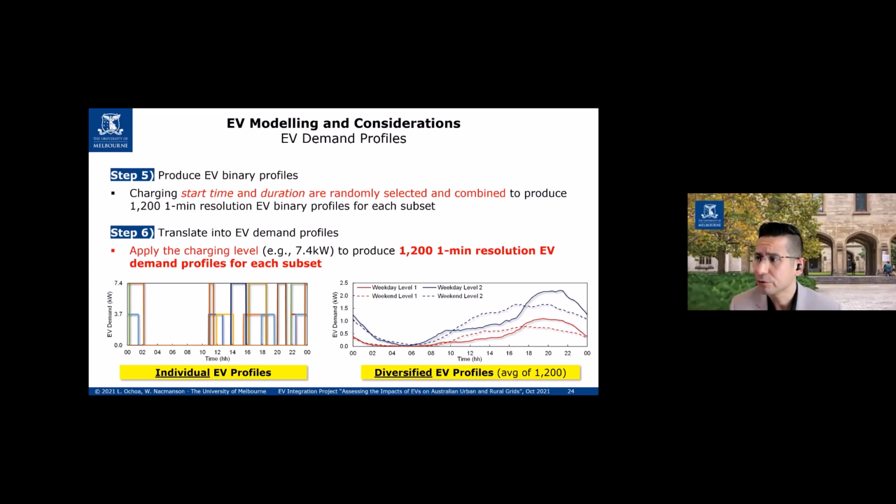Are voltage issues reduced with three-phase charging? That's a great point, Peter. I believe so. Voltage issues will be reduced with three-phase charging, and the reason for that is that unbalance plays a role here. Everything that we have done here are with single-phase connections, and that has the chances of increasing unbalance. If you have three-phase charging, it means that it will be balanced among the three phases, and that will have lower impacts. We know that for sure. We know that already with solar photovoltaics, so the same thing will happen with electric vehicles. Now, you cannot suddenly change the single-phase connection of houses to three-phase, though.